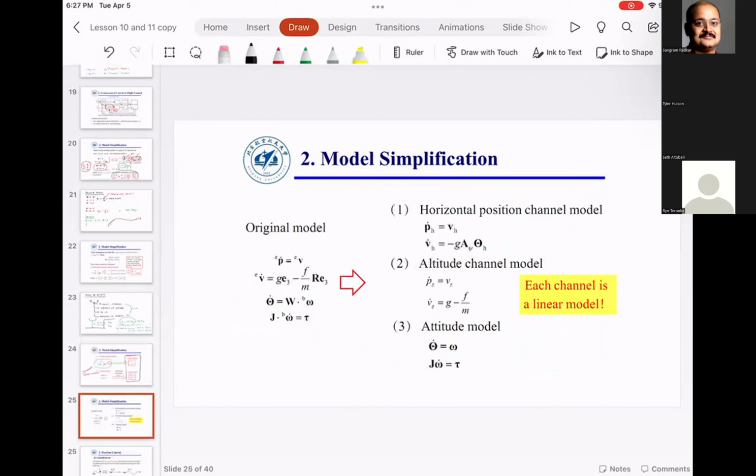And again, there are additional complications that arise when you use gain scheduling. Like how do you switch? What is the switching algorithm? You can decide switching based on some sensor values, some parameter values, or basically the maneuver the quadcopter is going to do.